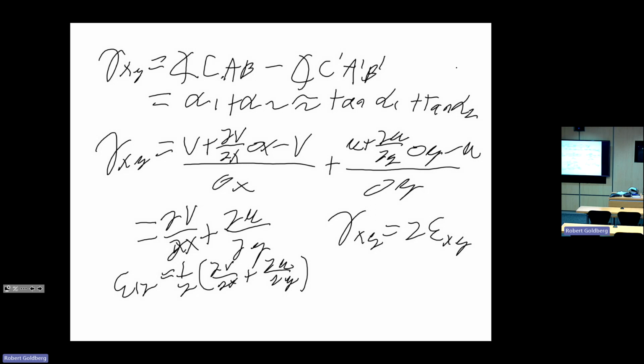So when you're doing constitutive equations and that type of thing, fundamentally constitutive equations will always be done in tensorial strain. So sometimes you'll have to convert from tensorial shear strain to engineering shear strain. So just keep that in the back of your mind.